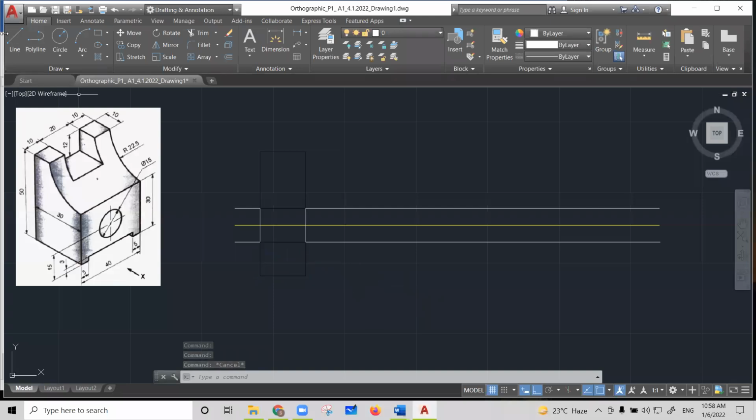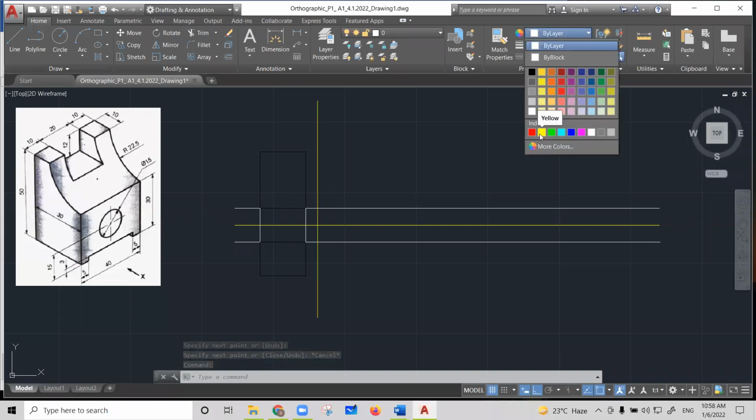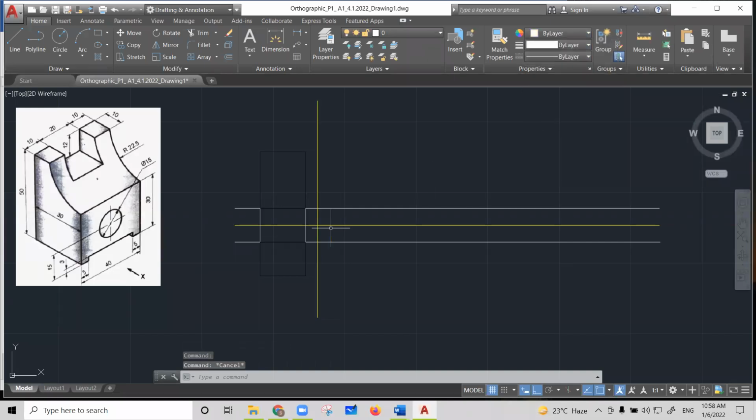Then go to line from here at a distance of suppose again 10 to 15 millimeters. You should get the line, not an issue. So this line becomes the X1 Y1 line, where that third plane, the auxiliary vertical plane, or we can say profile plane, intersects with the XY line. The intersection point, you can say suppose the O point. We are not going to name it, as naming is not required. Then I will go to the line.